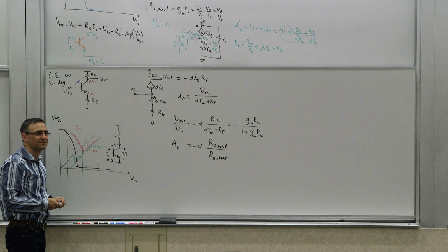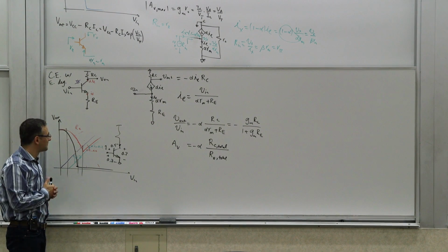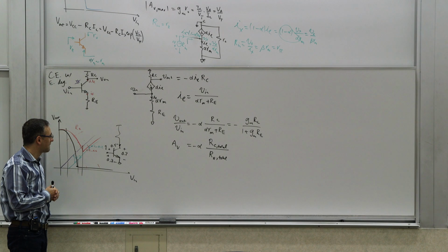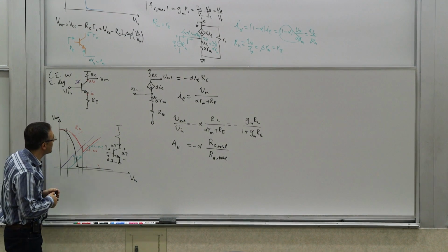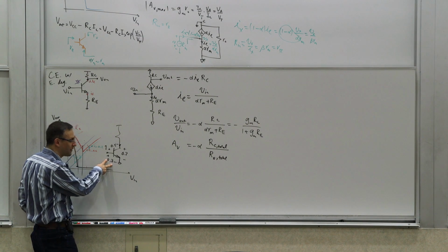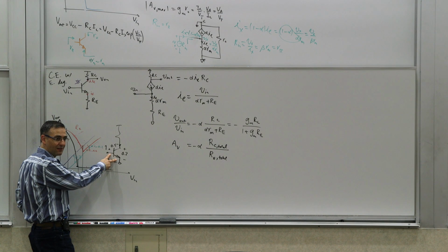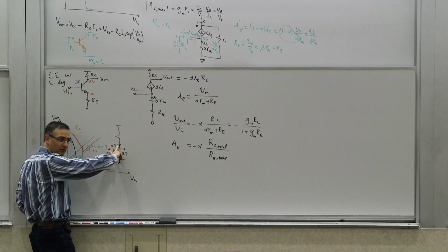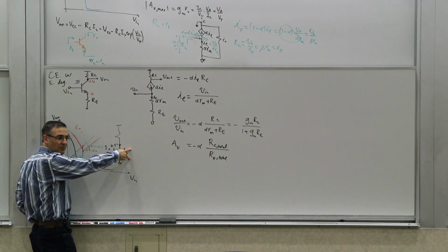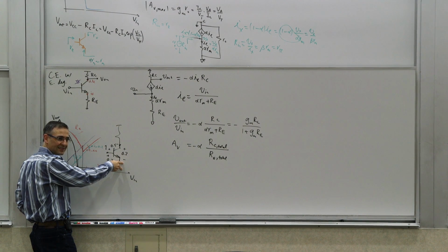So if you had a really small resistor and the gain was much steeper, then the second curve, the red curve, would also do that or not? Well, regardless, you can think about this voltage being around 0.7, 0.8, right? So if this voltage is 0.7, for this to turn on you need 0.5, which means this voltage is going to be 0.2. If there's no resistor here, this is going to happen.